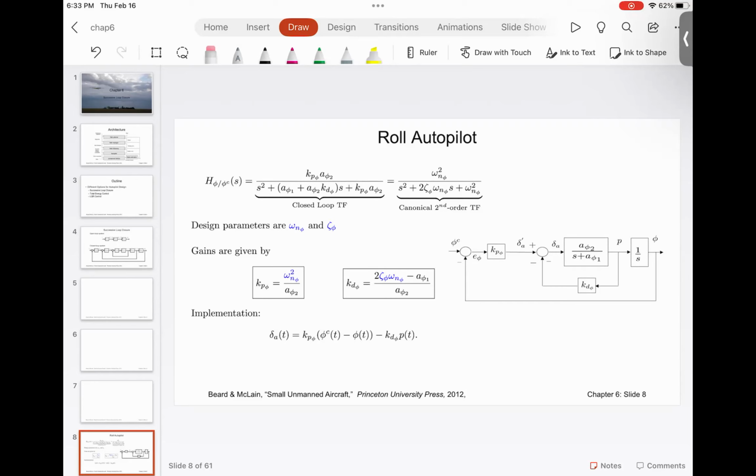The other way this can be done is, many times you have a small hole or small orifice here that restricts the resistance the fluid faces when it goes from one chamber to the other chamber. You can change the diameter of the orifice. Sometimes you can have external valves that open and close. For example, you can have a valve here and a valve here.